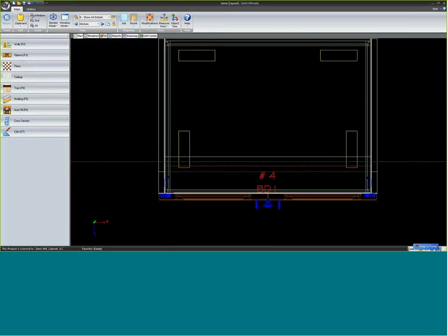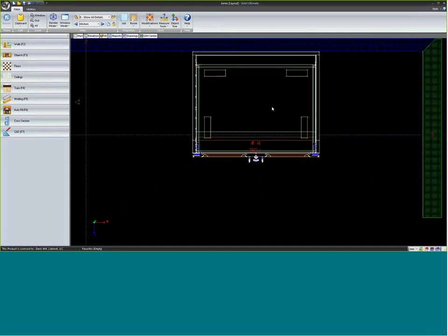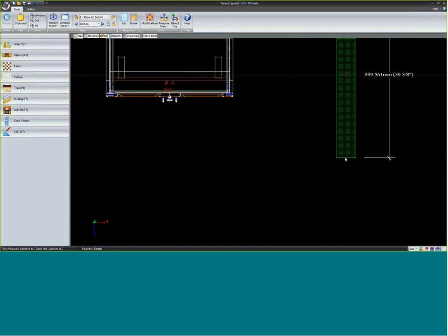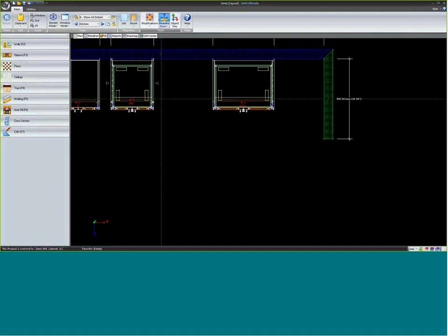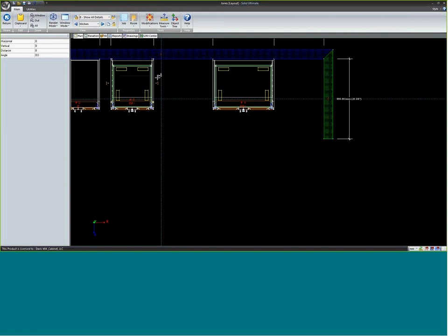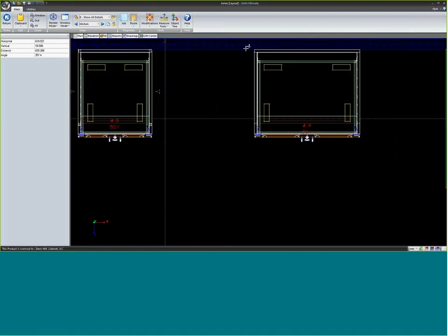But if I click on snap to points, see all the white dots that just showed up. Now those white dots become snap marks. You'll see them on the ends of walls, all of those things. Now I can draw a measure tool between any of these points like that. And then it's actually snapping. As I get close, you'll see a little white square next to one of those points, telling me that it's snapping to them.